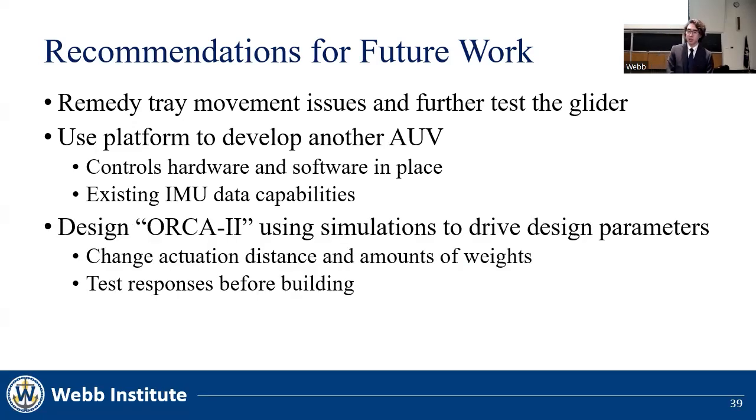Alternatively, the simulation and testing results could be used to design a theoretical Orca 2 glider. This would best be done by changing the variables such as the amount of ballast and the distance the weight tray is able to move. Also, it would be beneficial to make use of the glider's simulations before construction to verify the design.